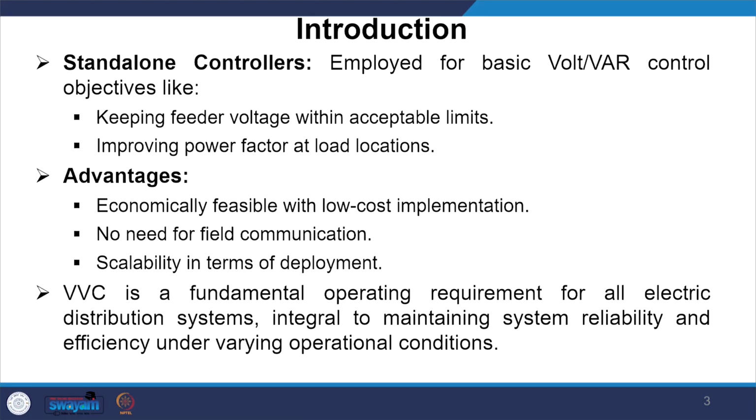Now, in case of standalone controllers, which employ the basic volt var control to achieve feeder voltage within acceptable limit and also to improve power factor at load locations, what are the advantages? Economically feasible with low cost implementation, no need for field communication, and scalability in terms of deployment is possible.